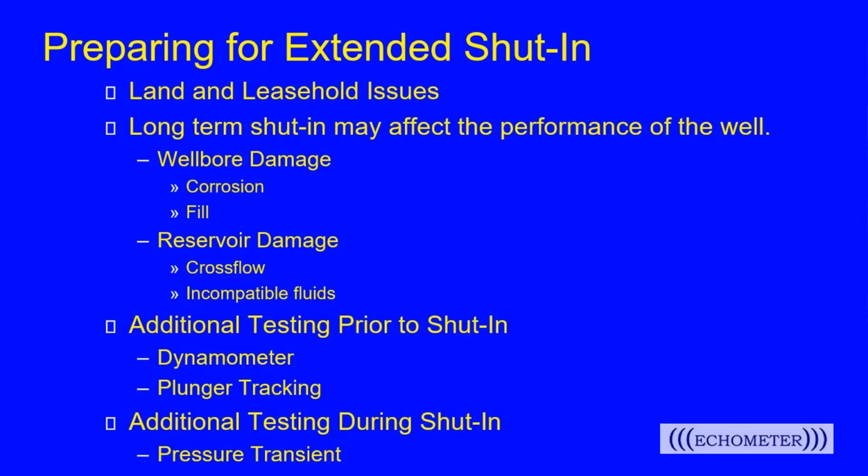Now, if we have time and the equipment, we can also do additional testing while the well is shut in. We can do a pressure transient test where we collect data over a period of time. We take multiple shots and we monitor the change in pressure over time. And that's a pressure transient test, and we can get additional information such as permeabilities, formation damage, and so on. And we'll have another session in the future to go into more detail on things like pressure transient testing.